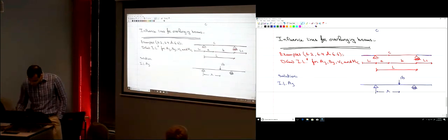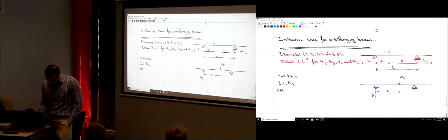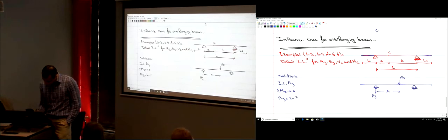Now, what's the influence line of AY? It's the magnitude of AY. How much is AY in this case? So to calculate AY, let's take the summation of the moments about point B. You will find that AY is equal to 1 minus x over L.